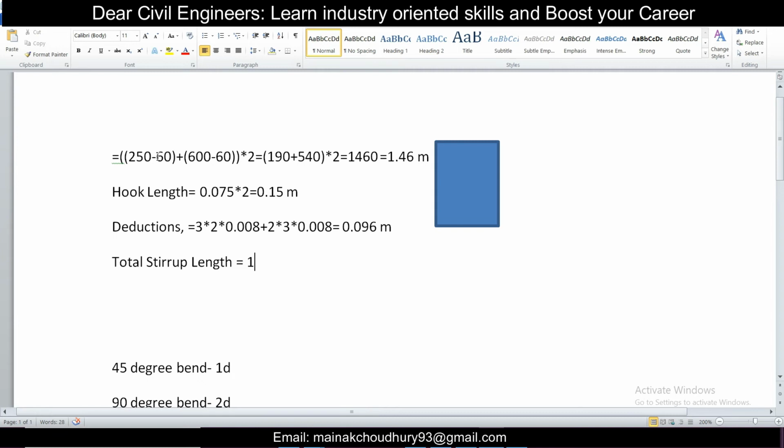We had calculated that total length, 190 plus 540 into 2, that is 1.46. So it is 1.46 plus the hook length, that is 0.15, all in meters, and the deductions.